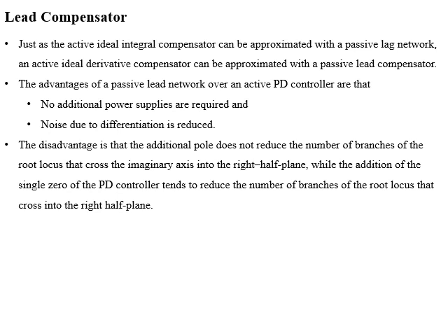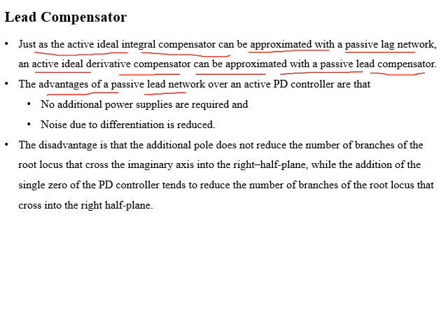Dear students, now we will study the lead compensator. Just as an active ideal integral compensator can be approximated with a passive lag network, similarly an active ideal derivative compensator can also be approximated with a passive lead compensator. The advantages of a passive lead network over the PD controller are that no additional power sources are required, and noise due to pure differentiation is reduced.